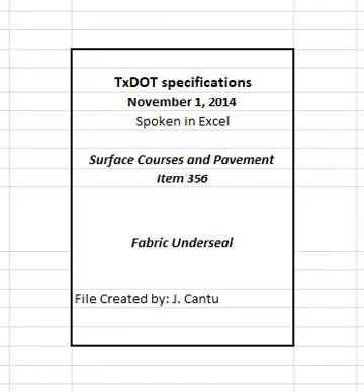Overlap longitudinal joints by a minimum of 4 inches. Apply additional asphalt binder to secure longitudinal fabric joints. 4.1.4 Blotter. Apply blotter as directed to the top of the underseal to absorb excess asphalt binder. Remove any excess blotter as directed.